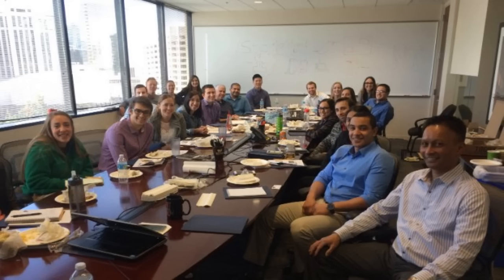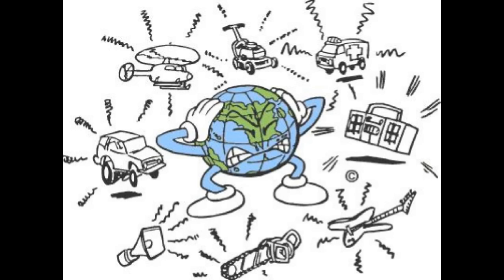The first important step is to define the problem, and that will require you to take a piece of paper and draw a sketch of your particular situation. What is the noise source? And if there are more, obviously you include them all, but we'll deal with one at a time initially in solving the problem. What is the decibel level?